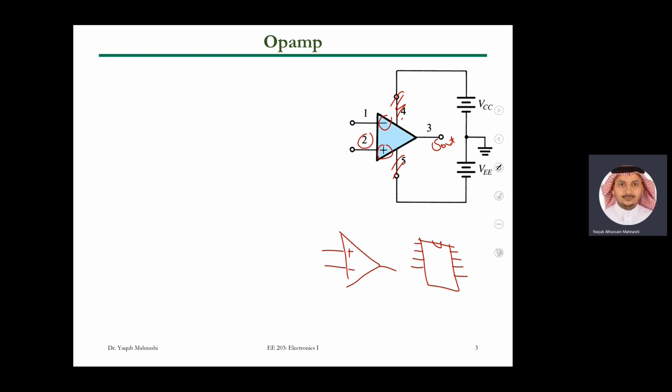Their amplitude may be in millivolts, so you want to amplify that to volts, so you can process them. And that's why we need an amplifier, to amplify weak signals. This is one application. Another application can be a filter. You can use the Opamp to implement a filter. You can do a differentiator, integrator, whatever. And you'll study that more in implementation in the lab, inshallah, if you take the 272.